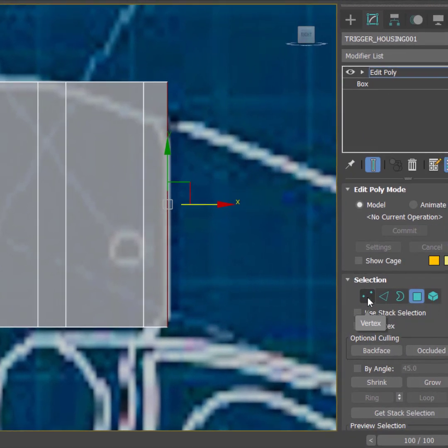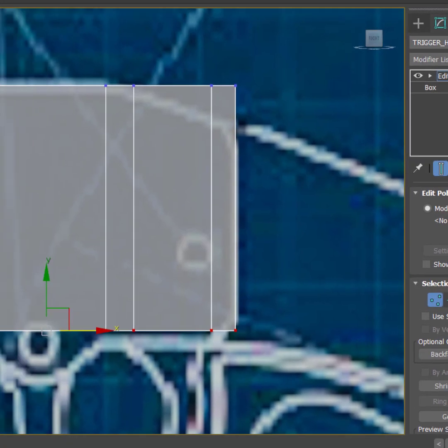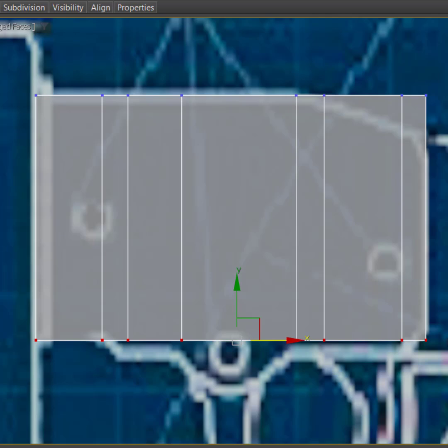Okay, so after doing a polygon selection and extruding it, the next thing to do is use the vertices here and then reposition the vertices that have resulted from the extrusions. For example, here at the top, I need to drag down these edges here so that they can follow. This one I need to assist, pressing R and then scaling that one.